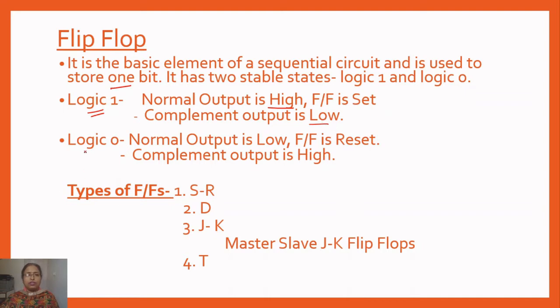Another state is logic 0. In logic 0, the flip-flop's normal output is low, and in that condition the flip-flop is said to be reset, and the complemented output is high.